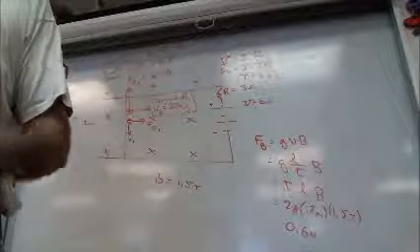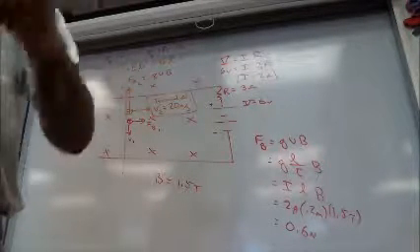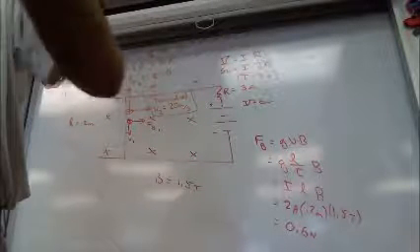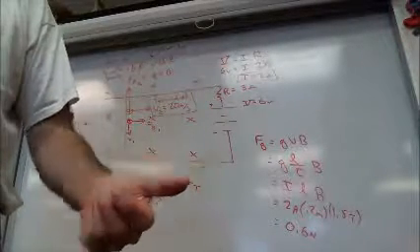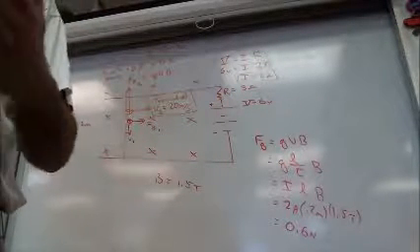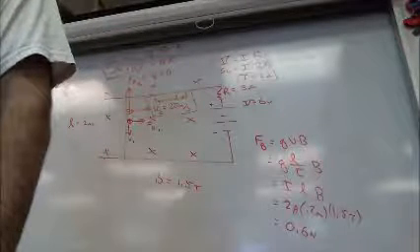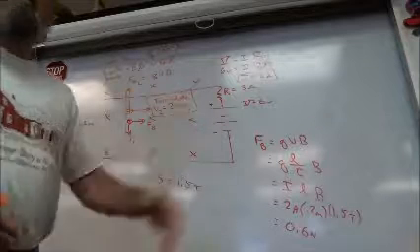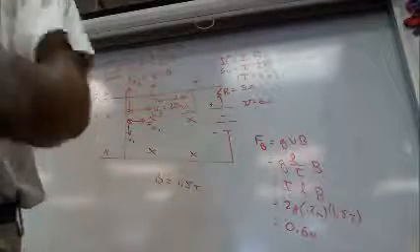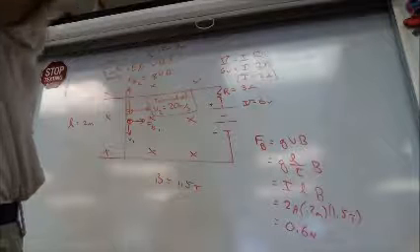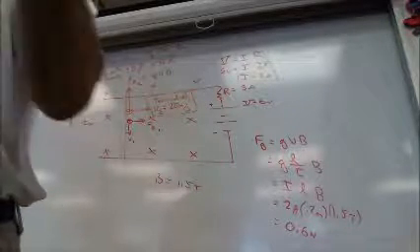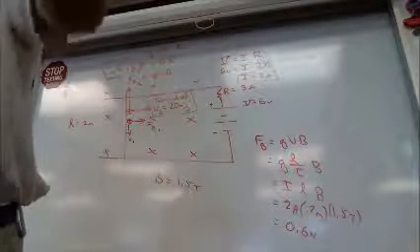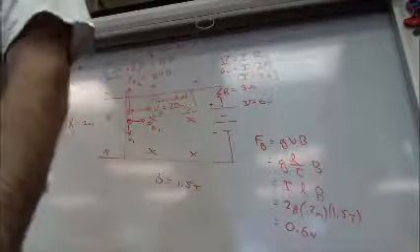How many of you have ever plugged in a vacuum cleaner, turned it on, and the lights in the room dimmed for a moment? Before the motor starts to turn, just when you turn it on, will you have a lot of current or low current the moment you turn the switch on? A lot of current, because you don't have any velocity yet. That's what's happening in your vacuum. You turn it on and there's a surge of current. Well, if the current is going into the vacuum cleaner, there won't be as much left over to go through the lights. Does that make sense? You're going to get a voltage drop in the circuitry in that room.